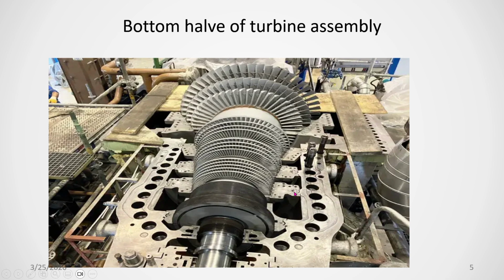Then once we put this guide blade carrier, you have to keep the clearances of the guide blade. You see that the rotor has the labyrinth seal here. The guide blade also has clearances with the rotor shaft. So you have to keep the gap of the guide blade carrier with the rotor shaft equal, up and down also. How are we doing it? These guide blade carriers normally rest on the threaded cup and bush, and there is an eccentric bush at the bottom of every guide blade carrier, so that you can tilt it to an angular position, and with this cup you can lift it up and down.